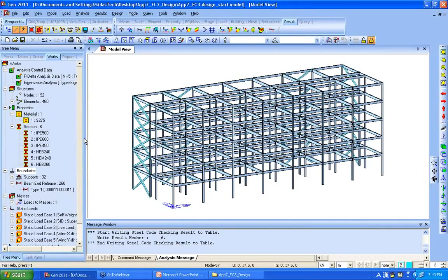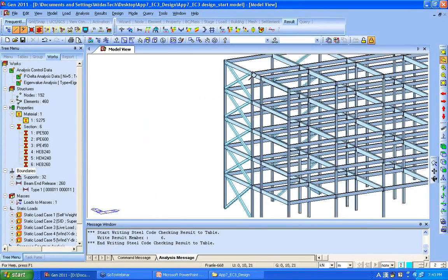And I will explain about the bracing. As you know, this is the bracing, and nonlinear analysis using the tension-only elements does not have any relation with the linear load combination. It is because the stiffness of the structure used in dead load analysis is different from the wind load analysis. In this case, we need to generate the static load case, including dead load and wind load. And as you know, this brace is a tension-only element, so we should generate the static load case including the dead load and wind load.